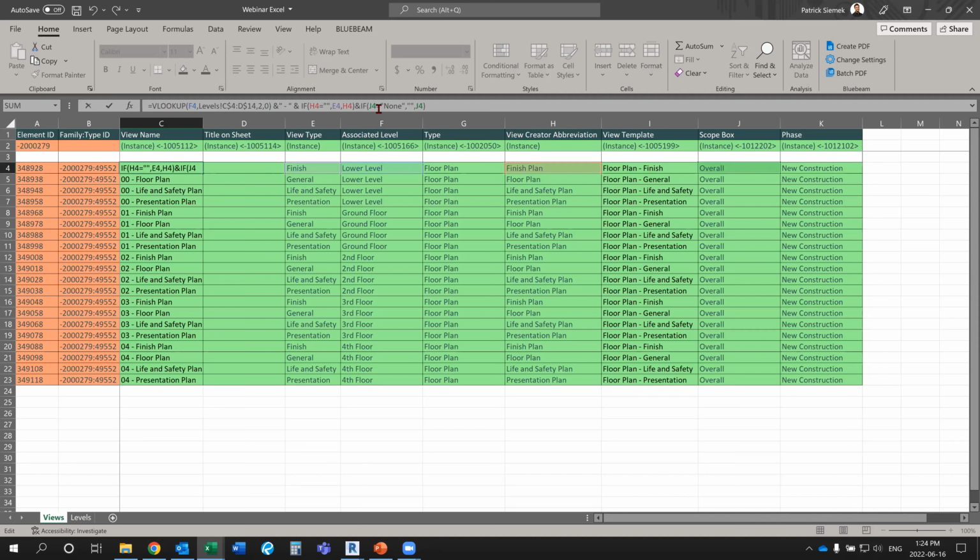I'm just going to add after this one another space and. So there we can now have the spacing, and I can drag that all the way down to my views. So again, as you can start to see, we could add additional naming conventions just using the parameters that are coming from the formulas themselves, and then having it inside of our views.